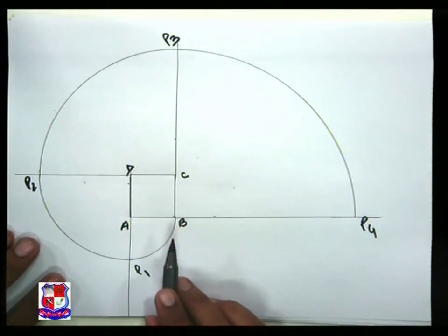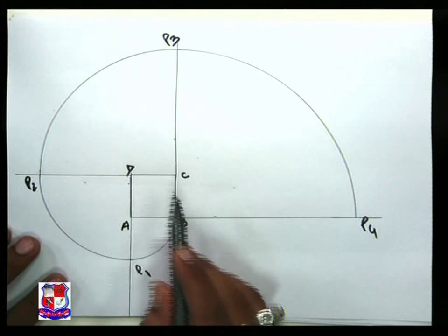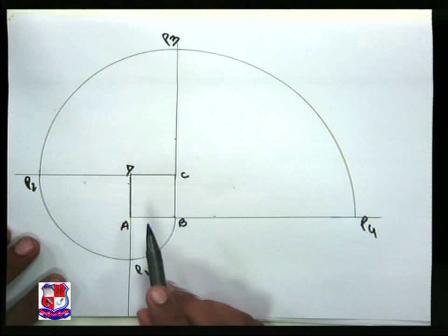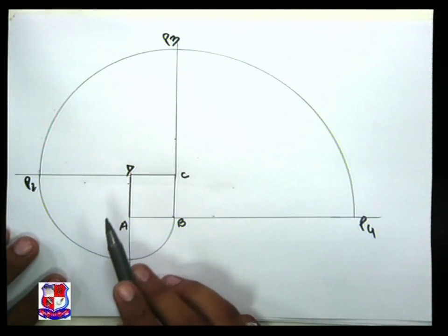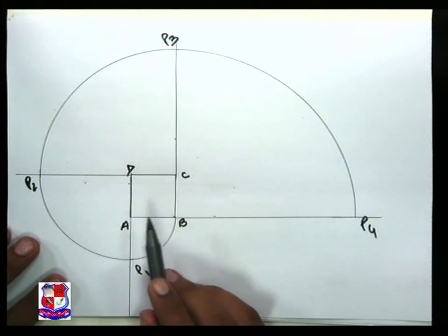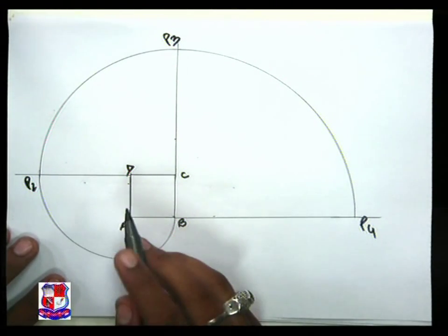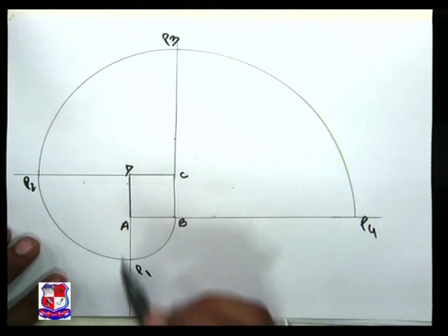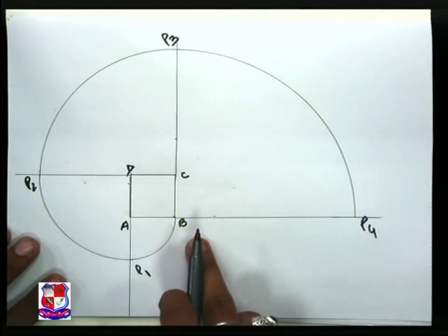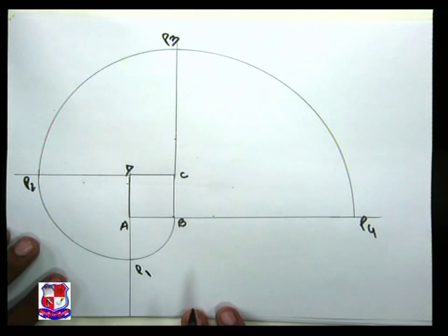Now let's repeat this procedure, how we can draw an involute for any object. Over here we need to draw the involute for the square. A square has all sides equal, and here we have sides of 25 mm each. Be sure to have proper perpendicular sides. I have drawn square ABCD. I have extended lines AD, CD, BC and AB. All the lines have been extended.